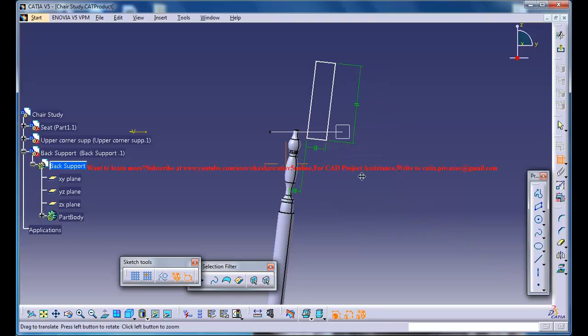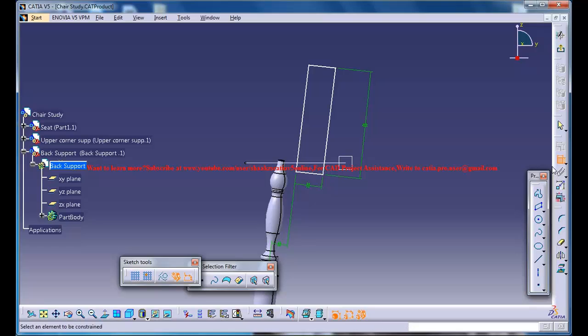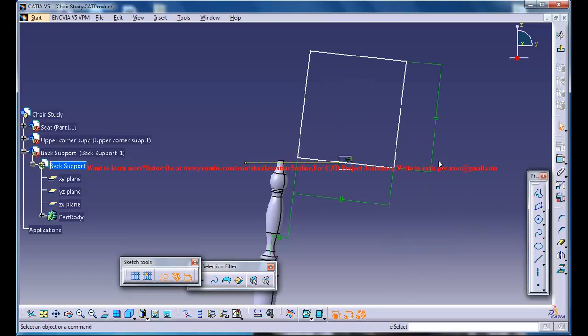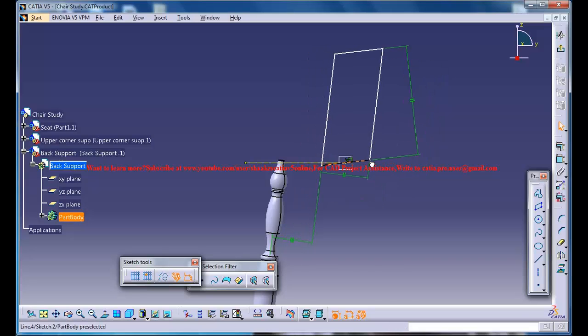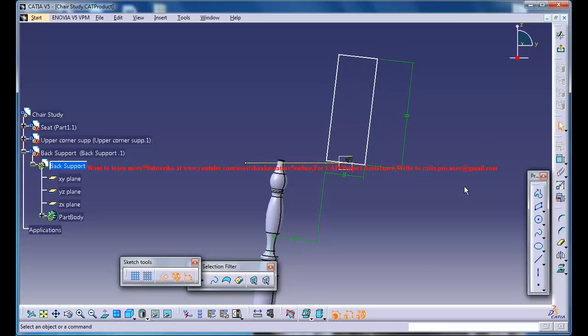Right, now make sure that this particular point, so for getting that point, just project this and make it dotted, and just select this line and make it dotted. Again, use the dimension, select this point and this edge, make it midpoint, and take this point here and pull it out this way. Okay, need to do like this line, and this line should be perpendicular.